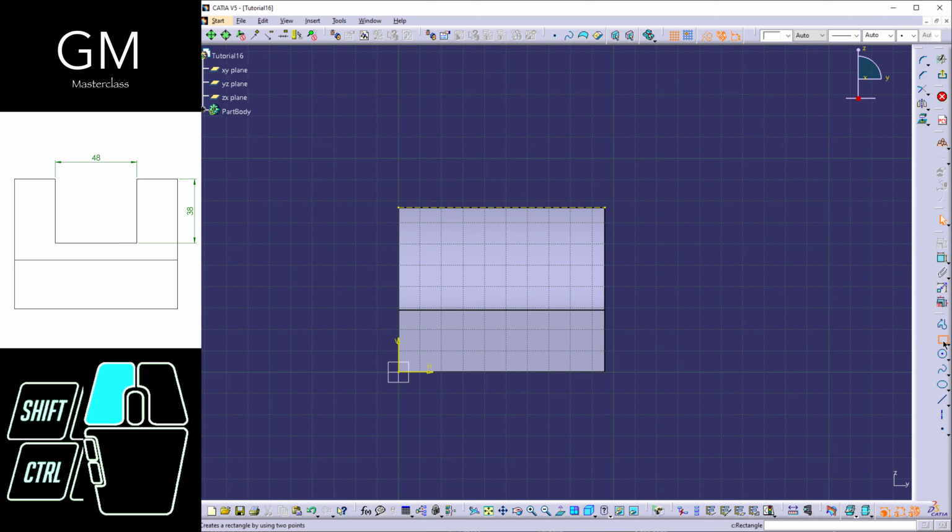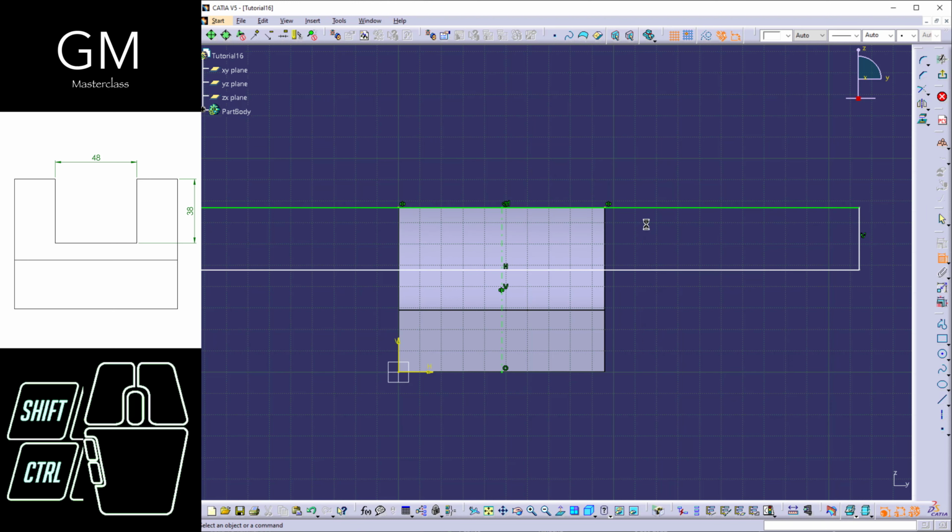Alright, so I'm gonna click on rectangle. I'm gonna deselect this option since I want this rectangle to be shown, and well, first I'm going to create a line with respect of this. This line has to be vertical, as you can see, has to be touching the middle of this line, the exact middle. Alright, so what I'm going to say is that between this point and this point is going to be a symmetry line that is going to be this one.